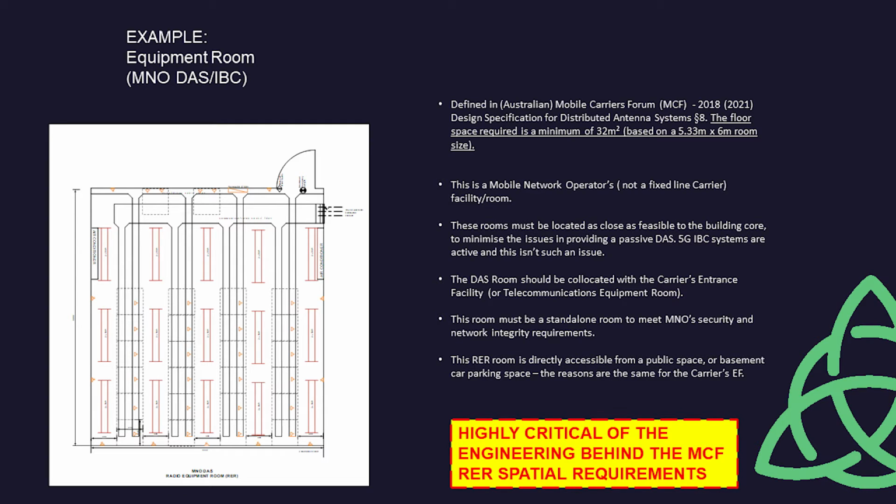Firstly, for the benefit of temperature control, security, and fire rating purposes, the equipment room must not have any windows or skylights. It is key to ensure that appropriate space allowance is made for equipment accommodation including access clearances, appropriate lighting levels, dust control, climate control, and door access. It is surprising how often these are overlooked. If the equipment room has climate control and other support equipment, these need to be alarmed. The alarm must be reported to a monitoring desk, especially if the air conditioning has gone off. The doors require access control, whether mechanical or electronic.